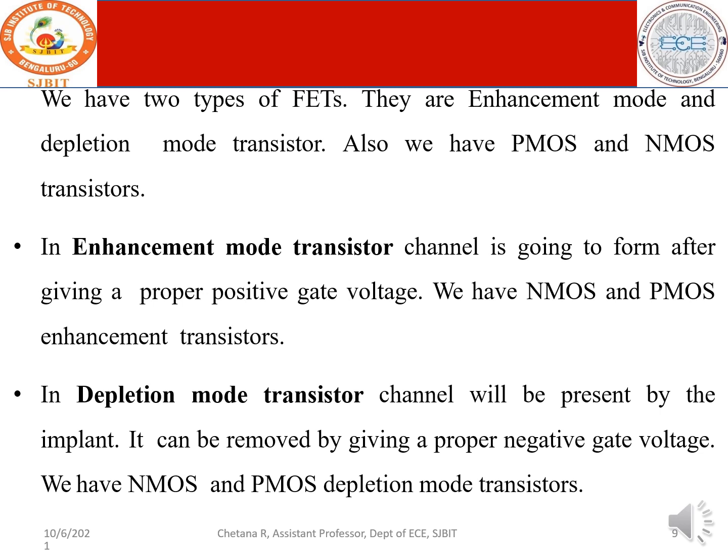Both source and substrate are grounded, which is at lower potential. Gate is always kept at higher potential, therefore it is given as VGS. So when you give positive gate voltage, it can create a channel, and that is how a channel gets created in enhancement mode.